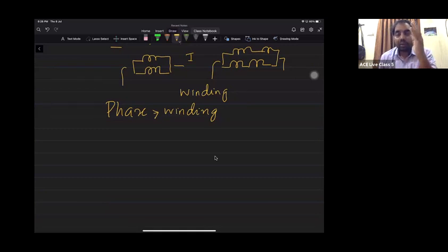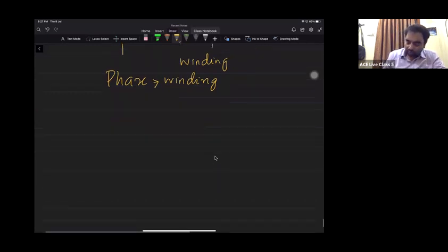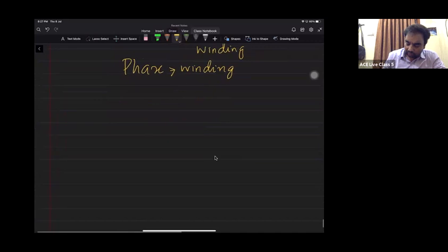When I'm talking about a three-phase machine, it means there are three windings placed on the stator, and those windings will have series and parallel connections of coils, and those coils will have turns, and those turns will have two conductors which are under a 180-degree shift. Is it clear? Confirm me, all of you. Yes. So can I say two conductors? I'll write a note here. Two conductors.